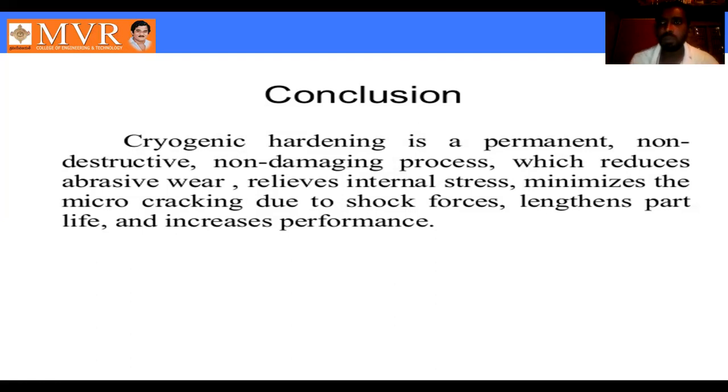It reduces abrasive wear and relieves the internal stresses in the material. So the internal stresses are also removed in cryogenic heat treatment procedures. It minimizes micro cracking due to shock forces. Why? Because when we apply a high load on a material, some cracks automatically appear. So cracks due to shock force are also minimized.